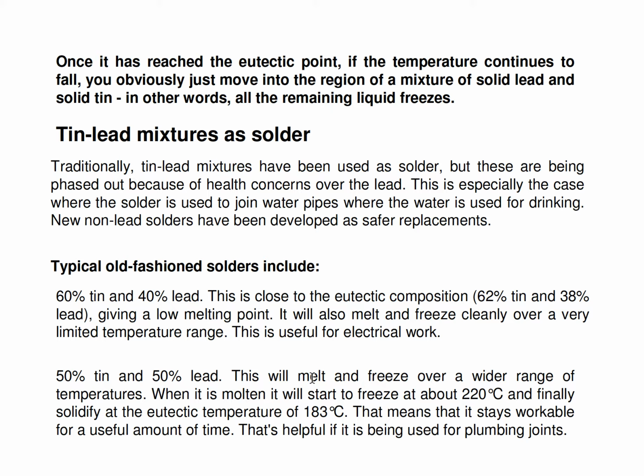When it has reached the eutectic point, if the temperature continues to fall, you obviously just move into the region of a mixture of solid lead and solid tin. In other words, all the remaining liquid freezes. So I believe this can be applied for freeze drying or other freezing applications.